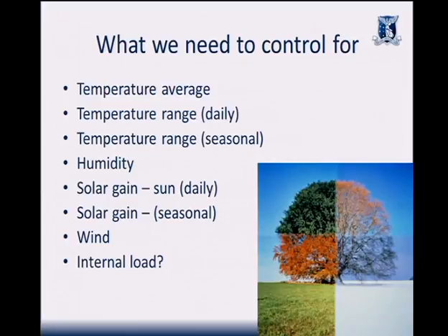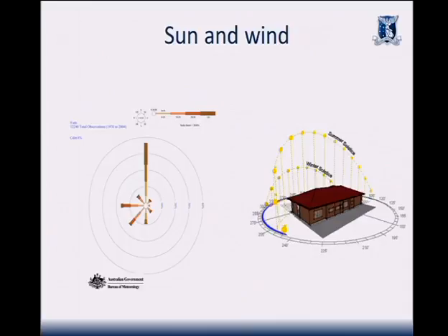Wind effect as well. We're relying on the wind to be our ventilation and our cooling system, and we live in an environment where there's very little wind for whatever reason. Well, that's obviously not going to work too well. So there's a lot of dynamic aspects that we have to deal with when you consider that the internal environment is largely static. So we want a fixed range of temperature, humidity, etc., with this external condition. I know you obviously have connected the fact that we're trying to use the best of what's available through the design of the house to create the comfort.